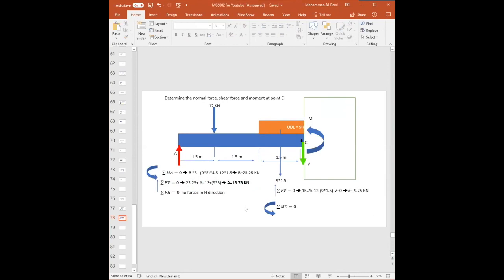All right, so for this question, counterclockwise, a moment around C. Remember, when we say around C, this moment will not be canceled. So please be aware, the moments under moments will be added. The only thing that will be canceled at that point is the effect of the shear force V, which will go away. So let's start writing the equation.